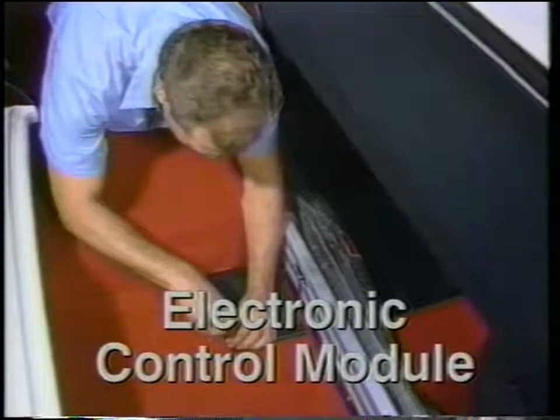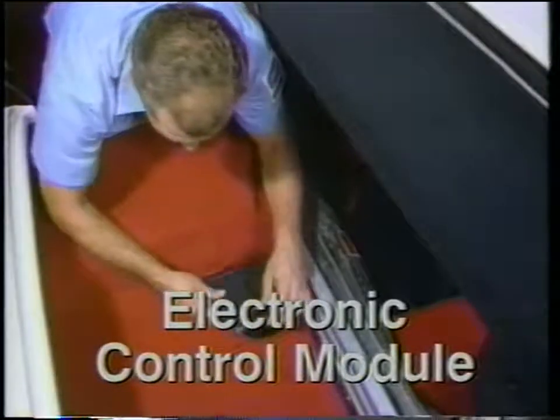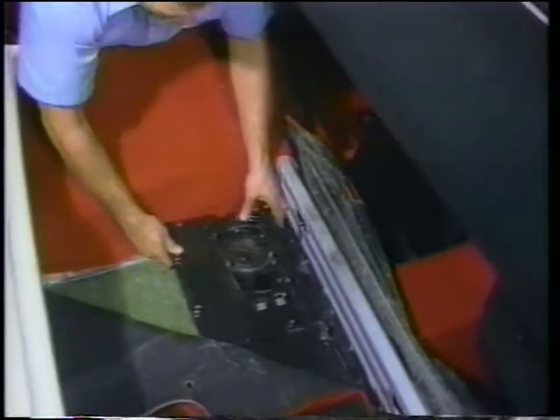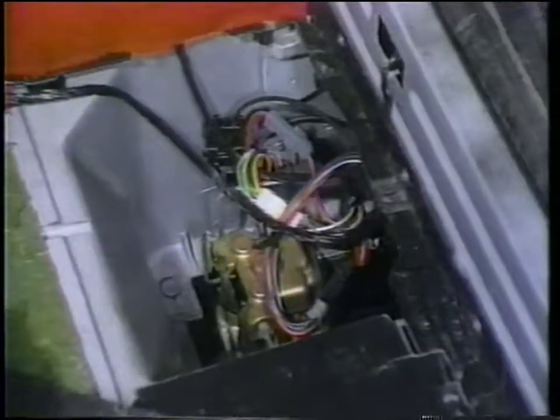An electronic control module is the brains of the system. It's often called simply the controller, electronic brake control module, or the common acronym EBCM. It can be located under the hood, in the trunk, or, as on this Corvette, behind a rear seat. An amber ABS warning light is typically located on the vehicle's instrument panel. This is in addition to the red non-ABS warning light for the conventional braking system. The sequence in which these 2 lights come on and go off can provide diagnostic clues.